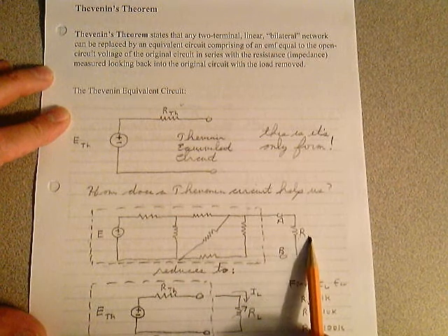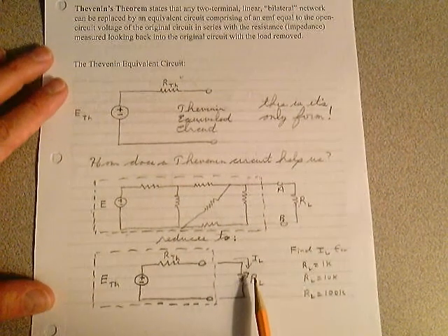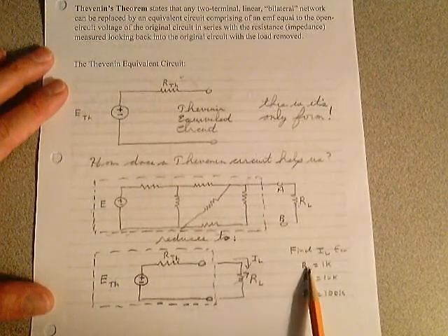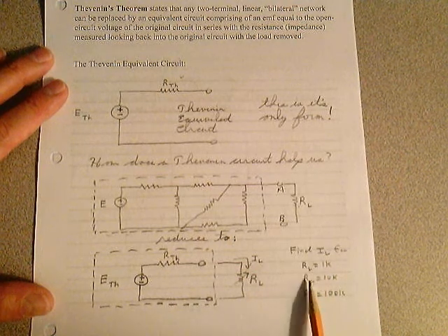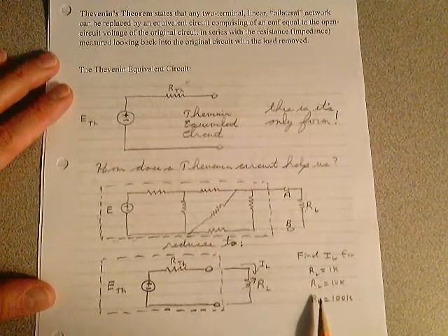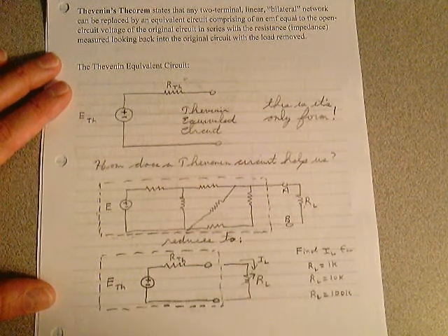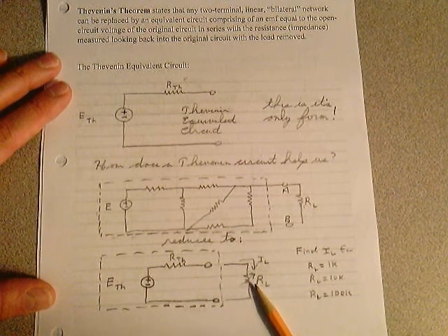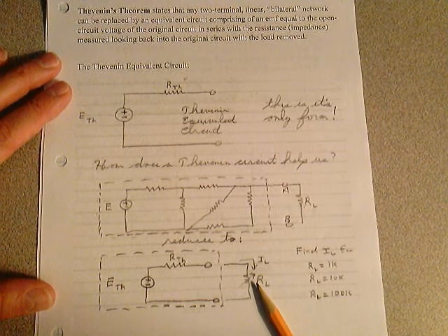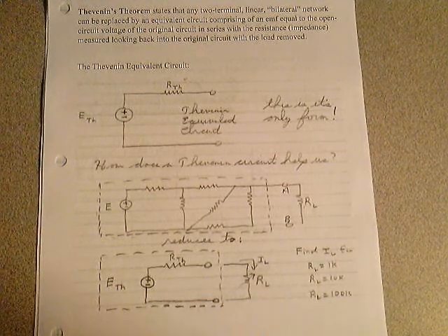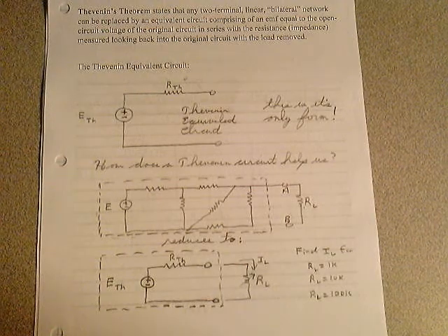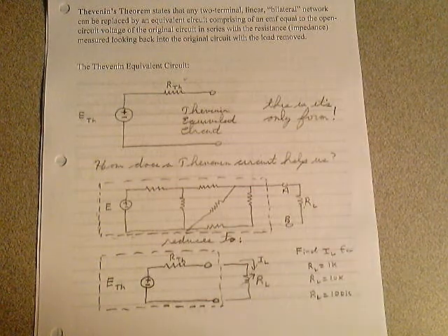Then you put this value of RL back on, and then you can change values of RL to 1K, 10K, 100K, and make simple calculations of current and voltage. And you'll see maximum power transfer as well coming up. So if you take a look, you don't have to turn there in the book, but I want to show you the power of Thevenin's theorem.